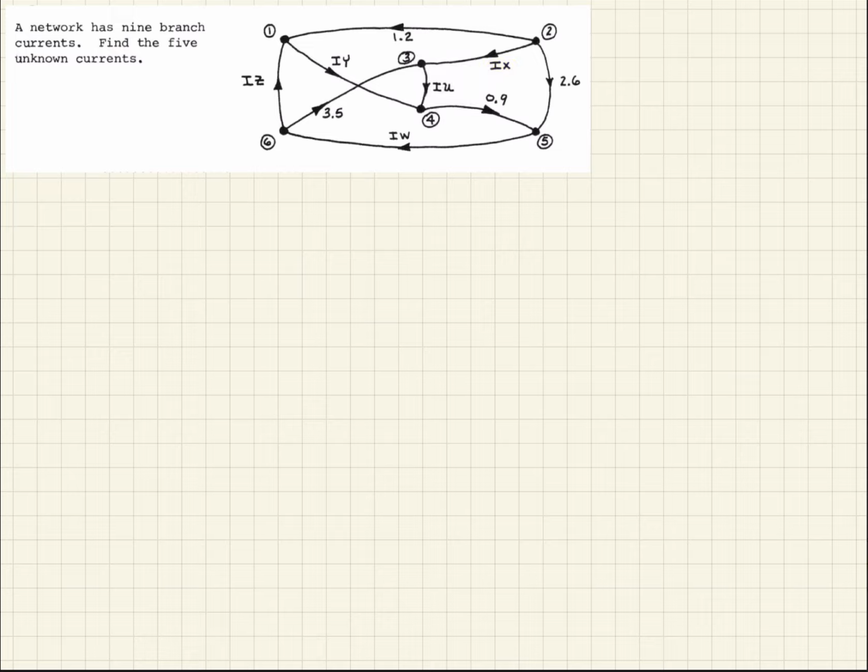So the first node we want to look at will be node 2. Remember, we have to conserve energy, which means we have to conserve current, which means that we have to account for all current. It can't be destroyed or disappear. So if we do that, we see that there are 3 branches coming in and out of this node. We're going to define current leaving the node as positive, and if we add all those up, they should equal 0.